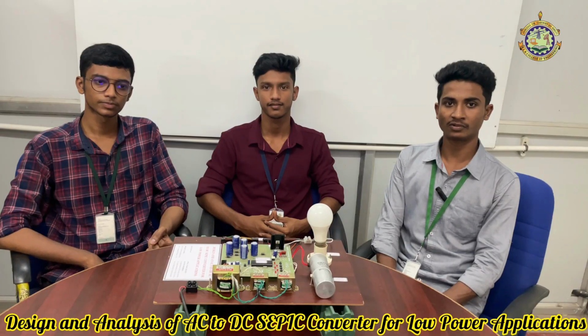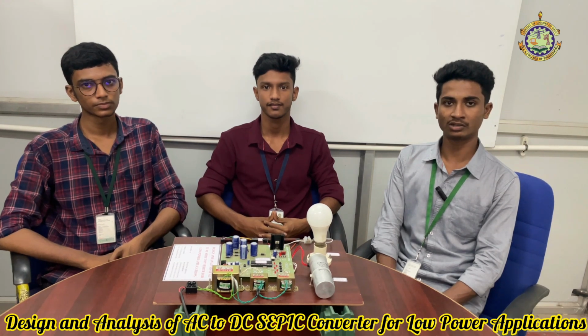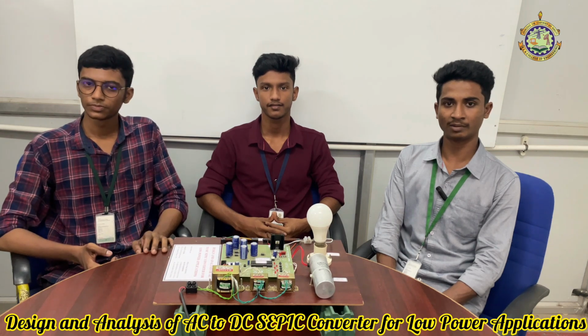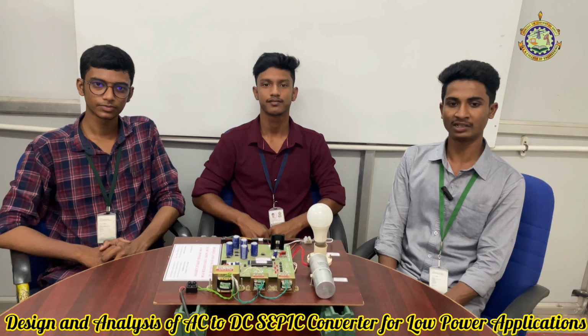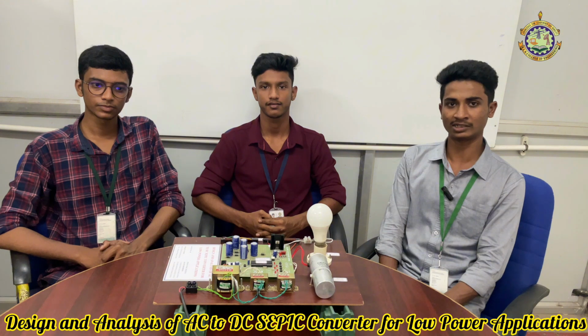We designed the converter for a 20 kHz switching frequency, a balanced trade-off between switching loss and size of passive components. Our calculated values are: duty cycle equal to 4%, inductors L1 and L2 equal to 0.777 millihenry, coupling capacitor C1 equal to 0.68 microfarad, and output capacitor C2 equal to 333 microfarad. Input current ripple is less than 2% and output voltage ripple less than 1%. These values were selected to ensure low ripple and minimal switching loss.